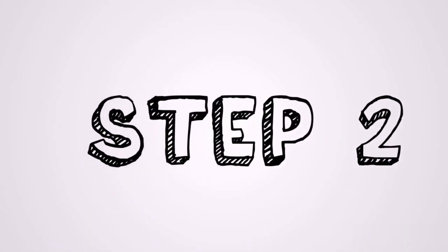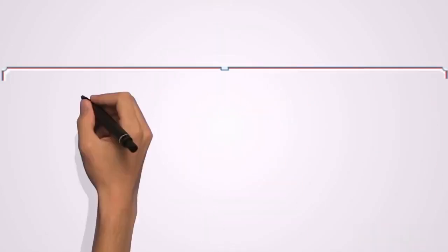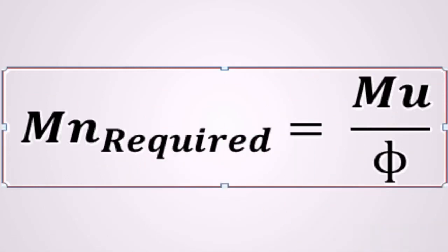Step 2 is we are going to assume phi equal to 0.90, which is the strength reduction factor, and we can compute the required nominal moment Mn, which is Mn required is equal to Mu divided by phi. So phi is the strength reduction factor while Mu is the ultimate moment.